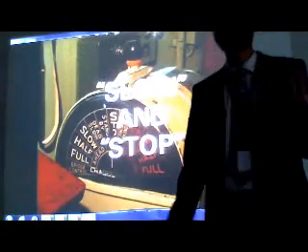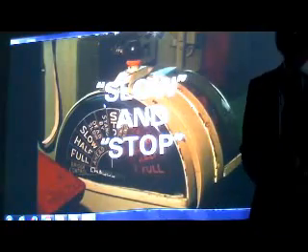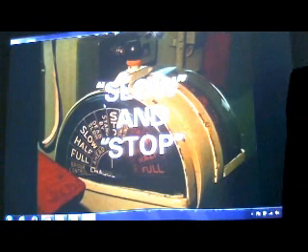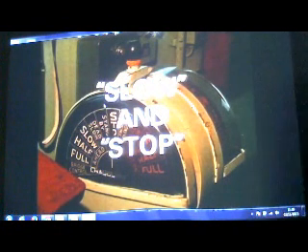So in our, if you want to write this down, in our bridges here, you will not going to see this in the telegraph: slow, dead slow. What you are going to see is 2, 4, 6, 8, and 10. 2 means 20% of your engine's maximum performance output. 4 means 40%, that is your dead slow head. 6 means 60%. 8 means full head, 80%. And 10 means 100% of your engine's RPM or performance output. So it equals 20, right? Roughly. It is not 100%, but the roundabout.